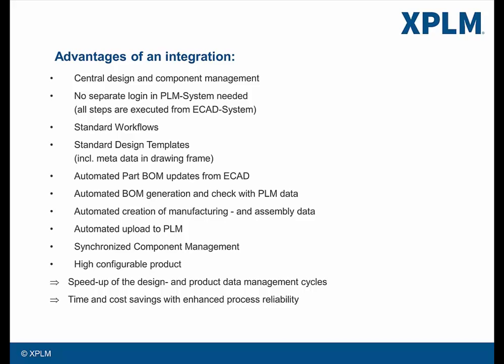Workflows are automated. For example, the generation of the bill of materials, a consistency check of it with the data in PLM, the generation of the PCB and pick-and-place information, and the transfer of those data to the PLM system are included. Also, the synchronization of the component information between the development library and the product lifecycle management system is a very important issue. Within that, not only misunderstandings or double work can be avoided, but also real process stabilization is reached. Within all these steps, Integrate can be individually adapted to your company needs.